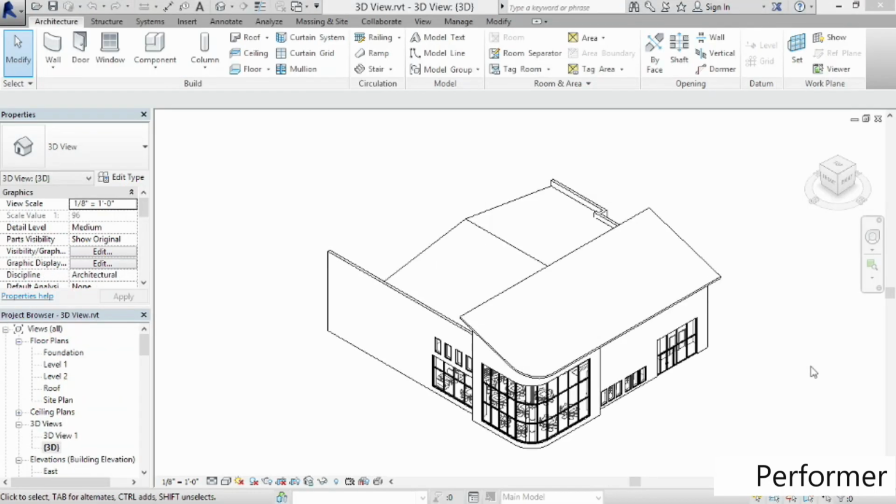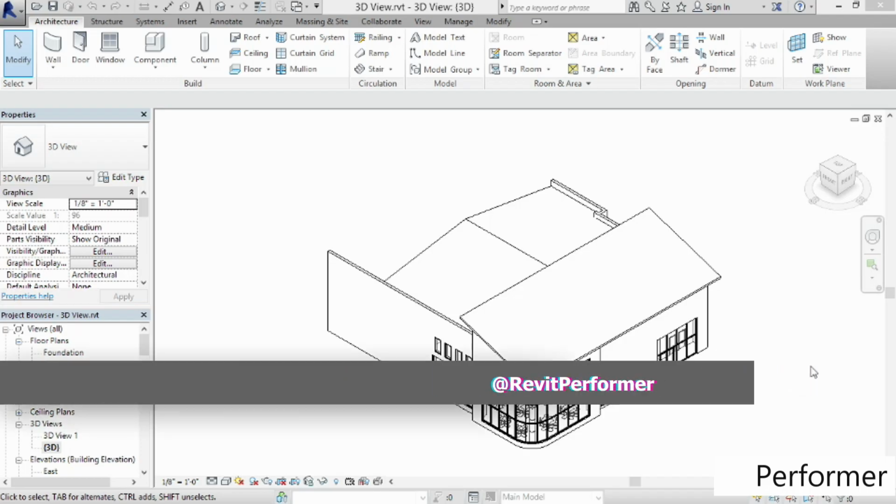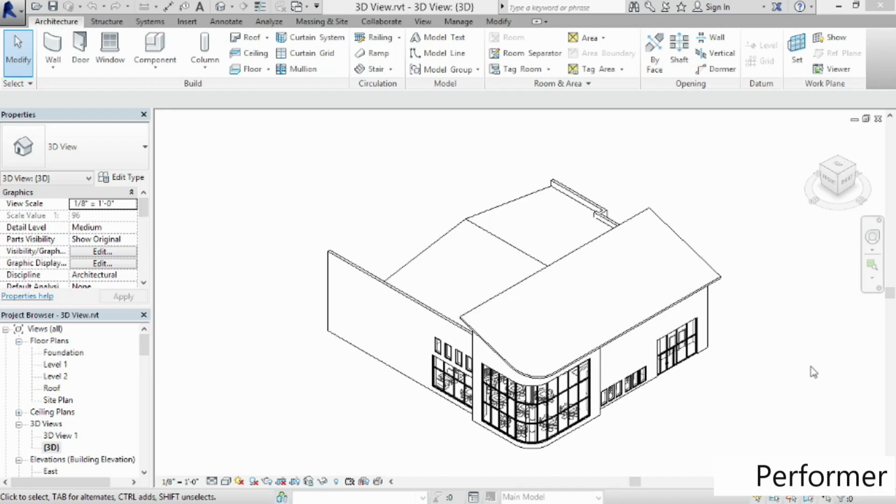We've looked at several different views for our Revit models. We've looked at floor plans, elevations. We created sections in the previous movie. We've even looked at some 3D views. But up until now, the 3D views we've looked at have either already been in the project or we've just simply relied on Revit to create the default 3D view. Let me just reiterate the steps to create a default 3D view. The icon up here on the quick access toolbar kind of looks like a little doghouse or birdhouse. That's the default 3D view icon.